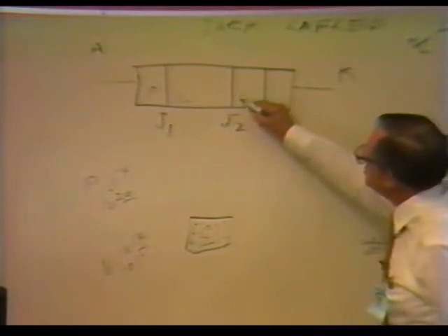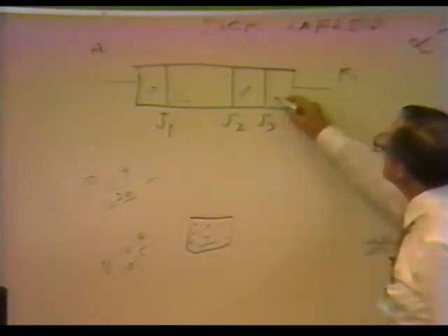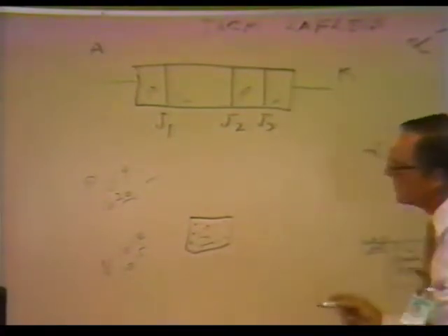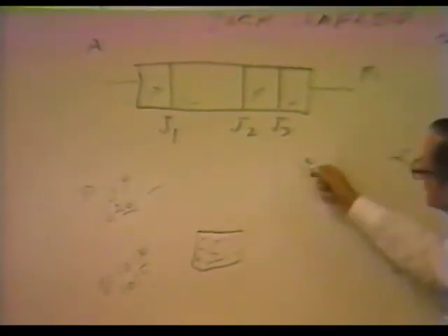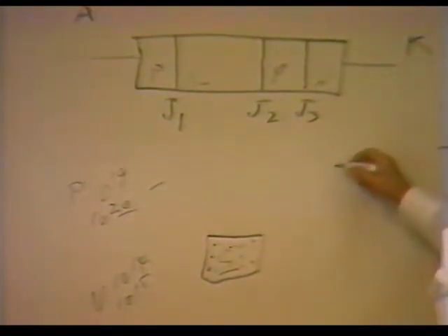When we come to the P junctions, it is close to this. And when we come to the N emitter, we want them pretty rich for the emitter. So usually in the N area of the cathode, we'll dope it at about 10 to the 20th, 10 to the 21, in that level. Okay. So you get an idea now of what we have in the doping profile of an SCR.